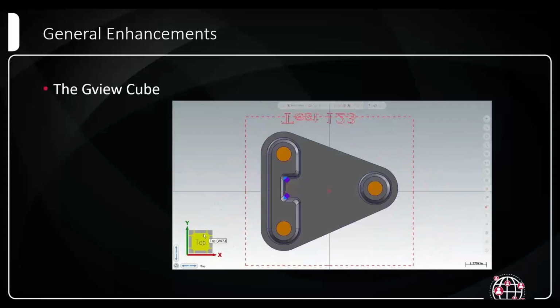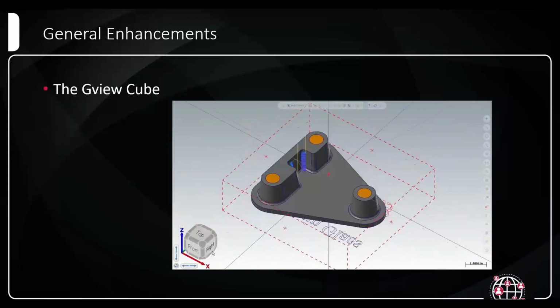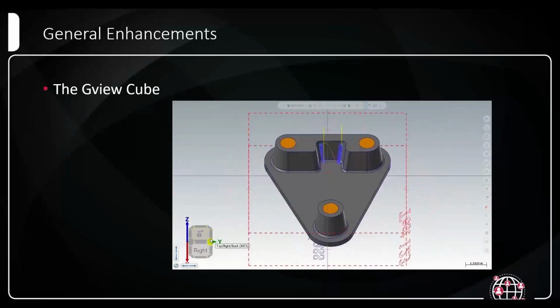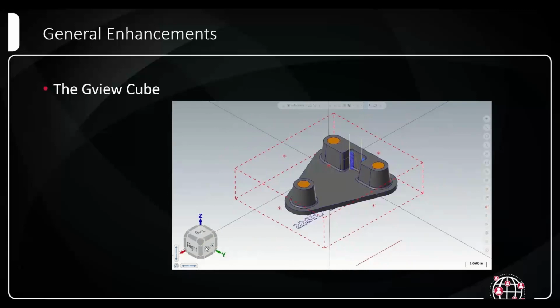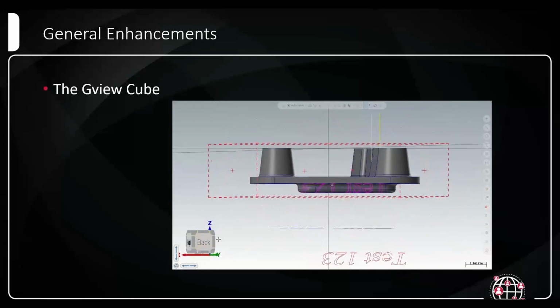And for those of you who are used to clicking on the gnomon in the bottom left corner for dynamic plane creation, you still can do that. You just have to click on the gnomon. Just be careful that you don't click on the cube.